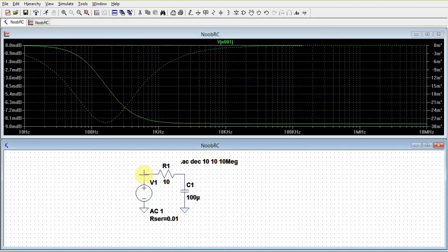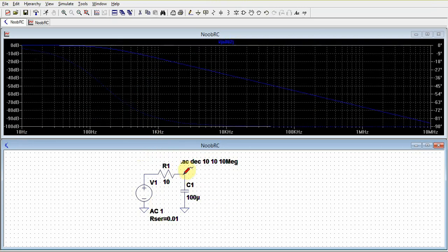Now this one has pretty much the same amplitude throughout the frequency range. So this is a very, very small drop as well, because of the impedance that we provided at the beginning. But like I said, it's really small. We're talking about millidecibels here. So that was a basic low pass filter. Of course, what we should do now is show you how to calculate real values.